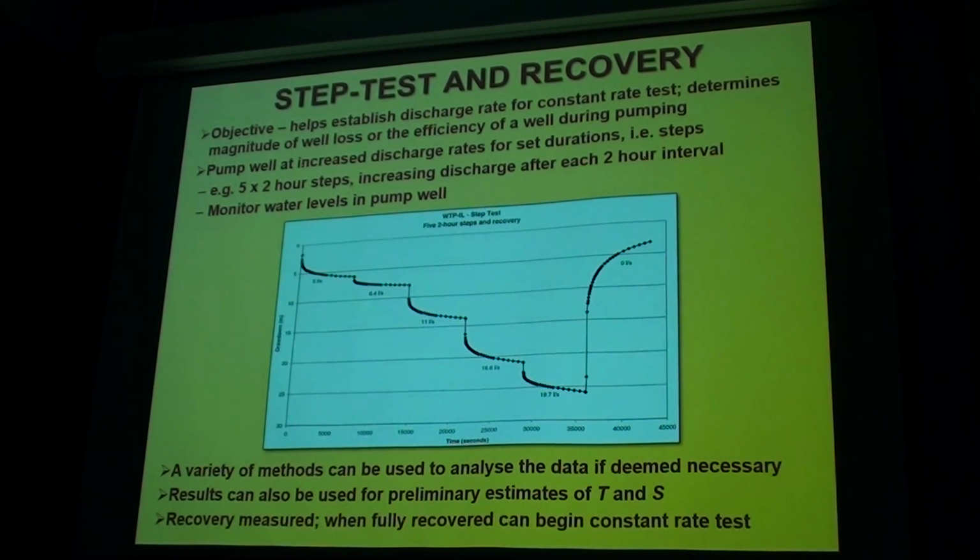Okay? But they'll only give you preliminary results because you're only short-term pumping. Each of these steps is only an hour, so they're not going to tell you a lot about what's happening overall for the aquifer. Your cone of drawdown isn't extended very far outwards. Okay? This hasn't established itself.